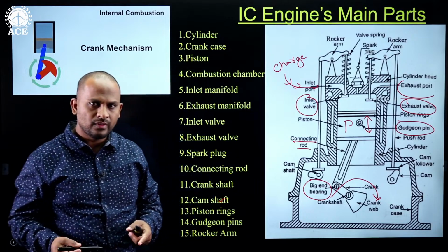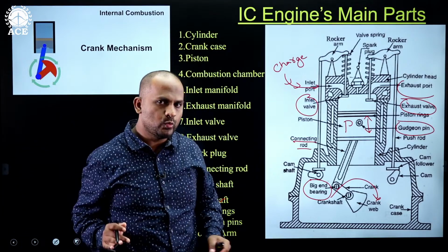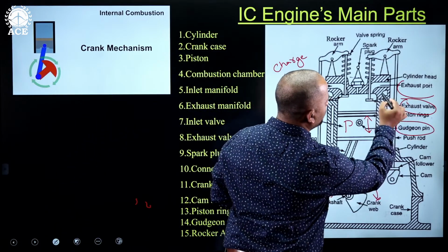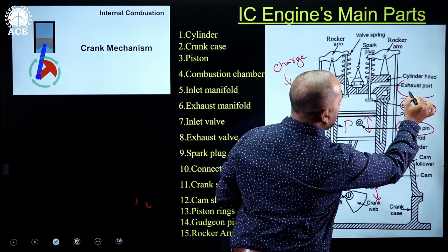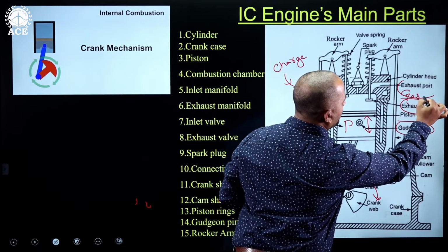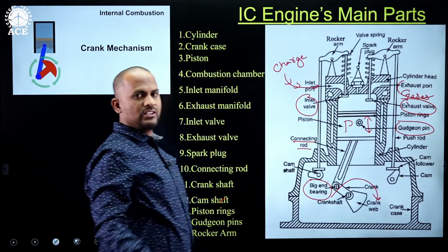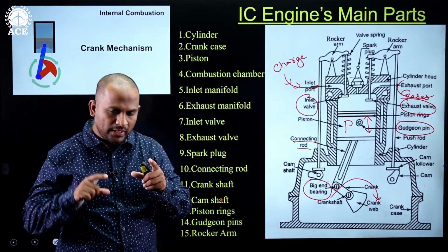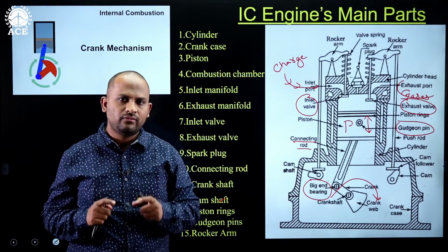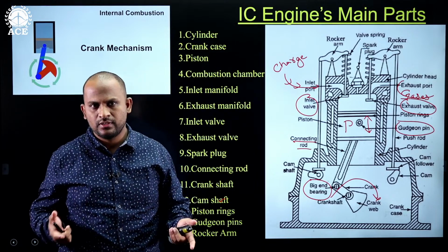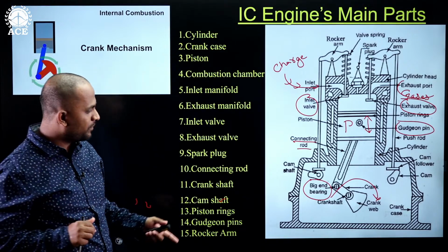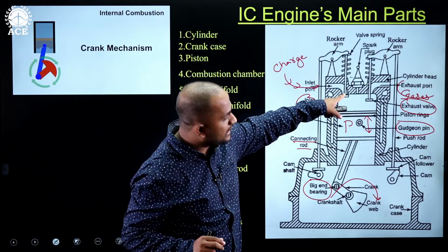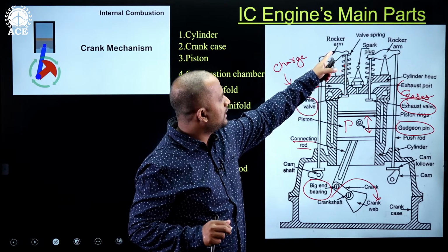After combustion, the gases have to escape outside the engine. For that purpose, through the exhaust valve, the gases are exhausted out. Now how does the actuation, the opening and closing of the inlet valve and the exhaust valve, take place? It happens with the help of a camshaft.